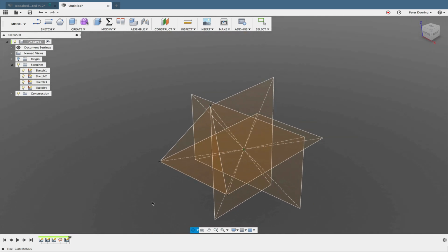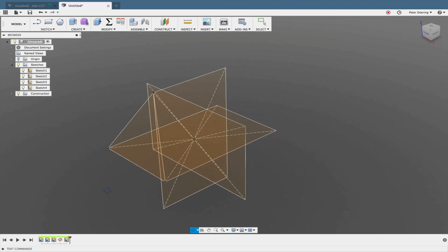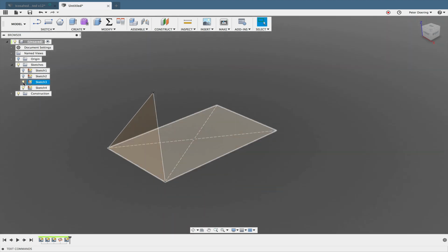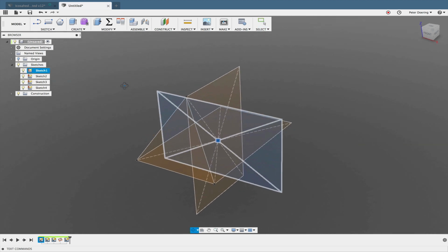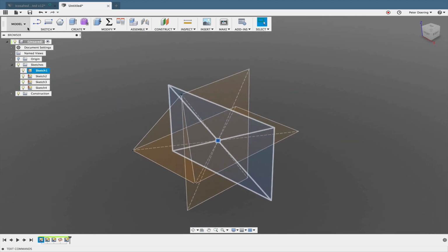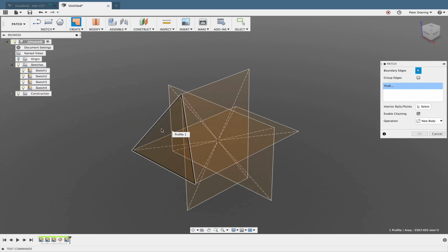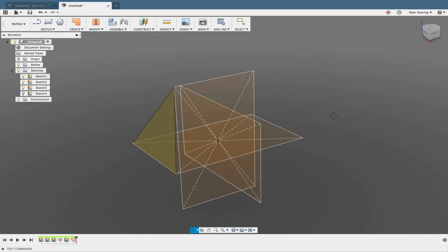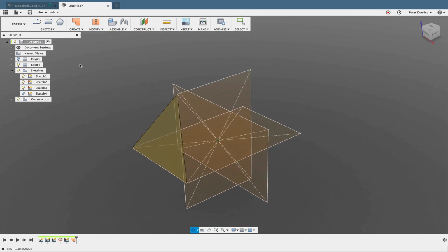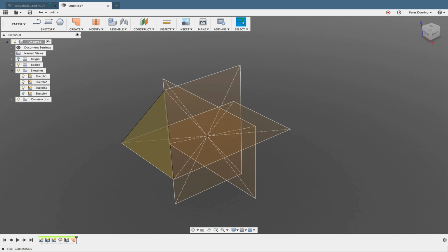There we go. Okay, so if an icosahedron would be all that we wanted to do, then we would basically almost be done. I could go to the patch workspace and create a patch here. Then I would just pattern that patch several times to create an icosahedron. So let me do this right now.